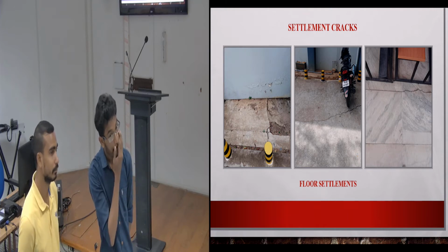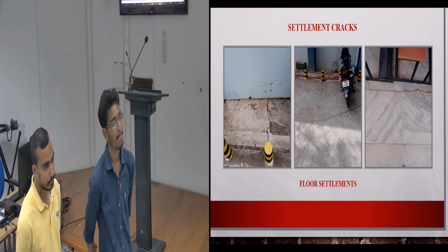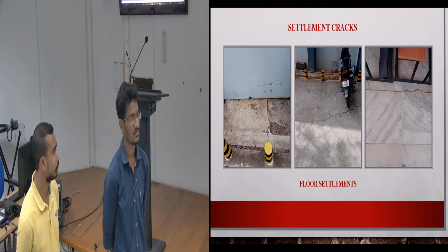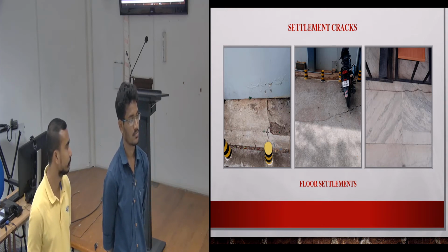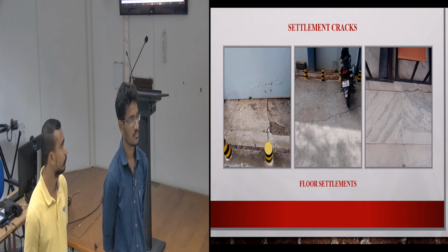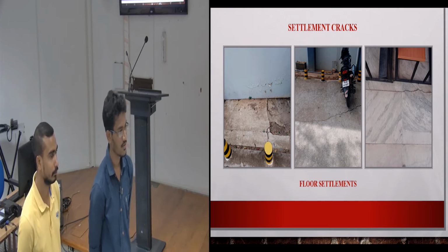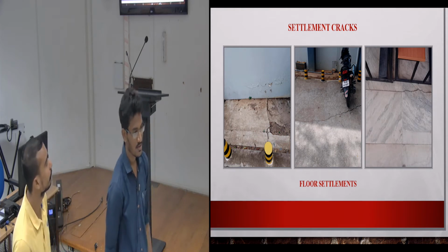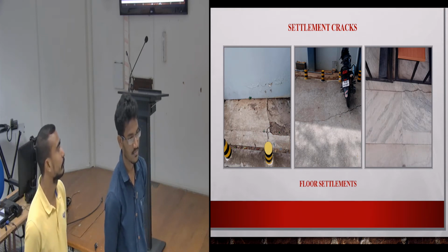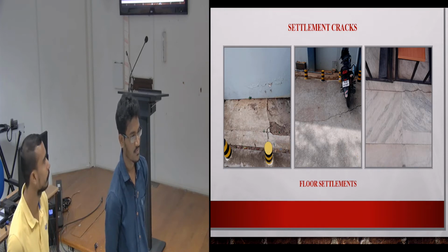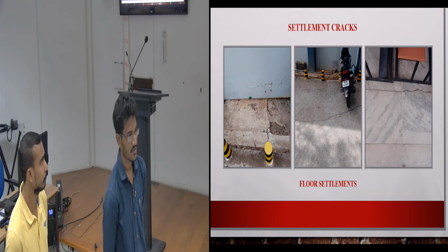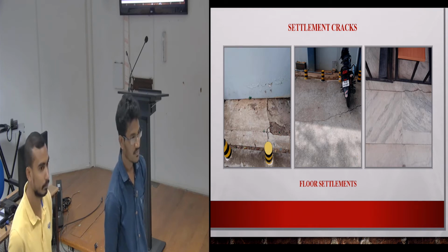When it is blocked, it would have pushed out. Suppose when that made-up soil loses its property, normally when the water is blocked, it might settle down. Subsidence. So in those cases, you can do an NDT to see if there's any hole underneath the slab. So there are ways that you can validate.